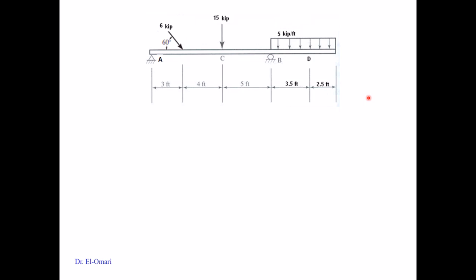We start by looking at it similarly to the method of sections for trusses. Whenever you find forces, you look at which side you would work with, because internal means that you have to cut and then use either side to work with. For the sake of exercise, I will use the right hand side. Although the other is much easier, I work with the right hand side for more exercise.